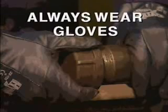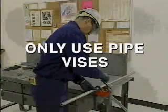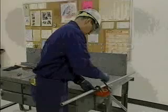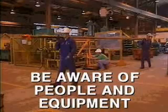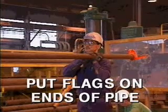Wear gloves to protect your hands from rough, sharp edges that could scrape and cut you. Only use vices equipped with special jaws for holding and protecting pipes. Conventional vice jaws can damage pipes. Be aware of the people and equipment around you when you're handling or transporting pipes. Put flags on the ends of long lengths of pipe so that you and others can easily see the ends and avoid damage or injury.